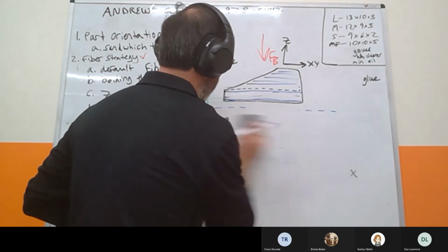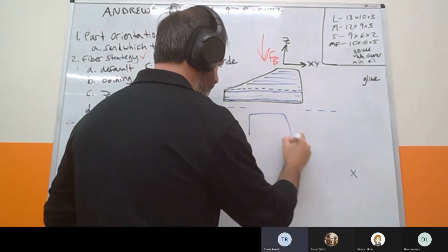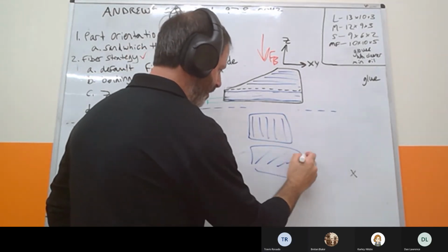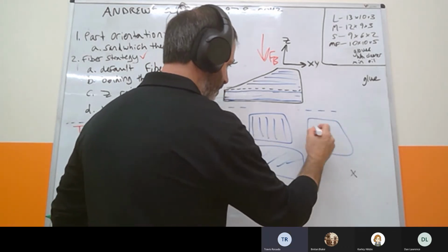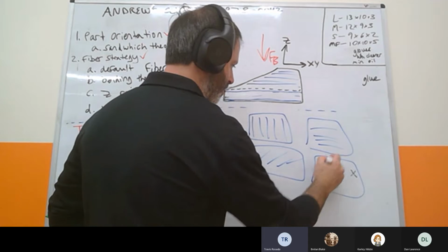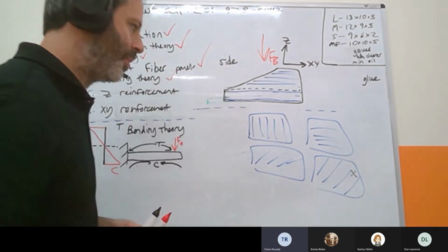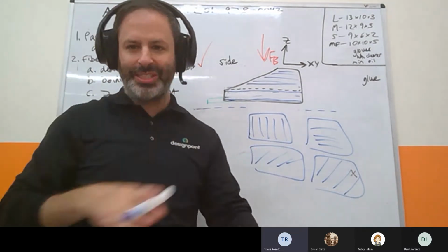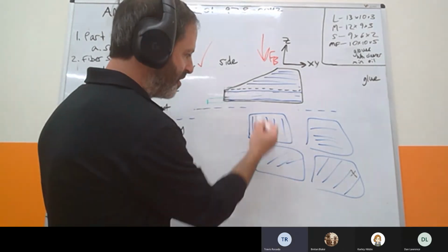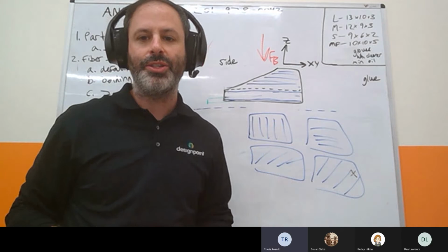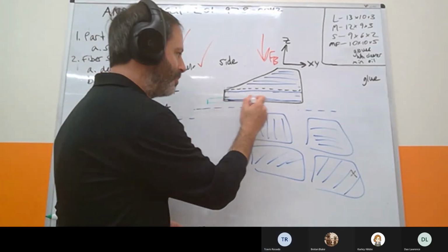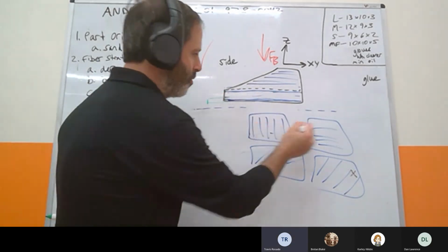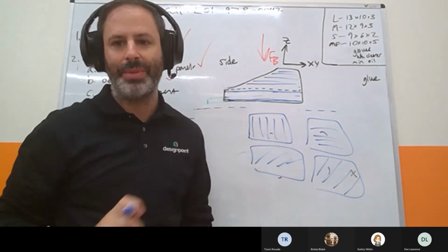Each one, like I mentioned, on the first one the fiber goes straight up and down. The second one, it's angled. The third one goes straight across, and then the fourth one goes the other way. So when you combine 4 of them in total, that's the full 360. That's the full cross hatching. And then once it goes to the fifth one, it would start repeating the same thing. So in an instance like this part here, when I say I'm going to put a panel on the bottom and a panel on the top, what I'm talking about is 4 layers that are cross hatched that combine to form that panel. So panel equals 4 layers.